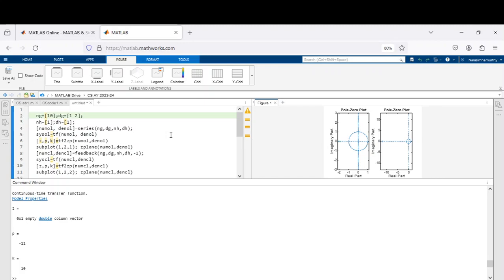And we want to write the system open loop transfer function in the form of s. So upon converting that numerator and denominator to a transfer function, we use the function TF of numerator, denominator. So this will actually return, if you can see here. I have already run it once, so this is what it is returning.